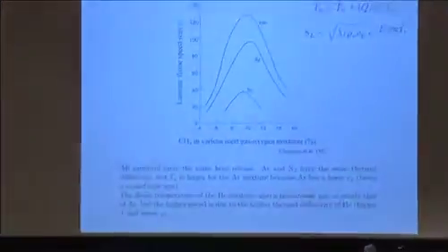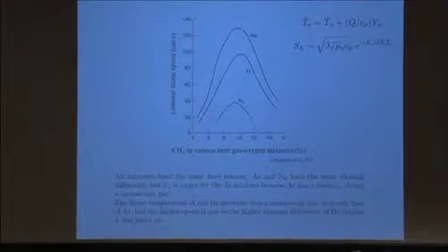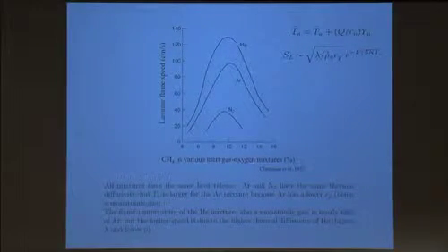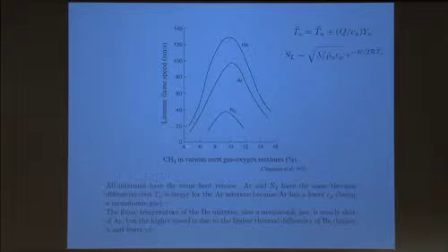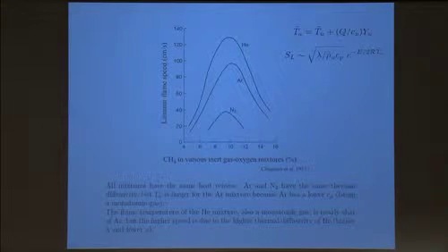Actually, there is another thing that is related to the first item. Let's go through that first. So here are the flame speeds. Again, it's measurement. Flame speed as a function of equivalence ratio for the same fuel, methane, but in various inerts, in nitrogen, argon, and helium. Well, it's the same fuel. It has the same heat release, so you may anticipate that they should have about the same flame speed. But this graph shows you the effect of this other factor in front of the flame speed.